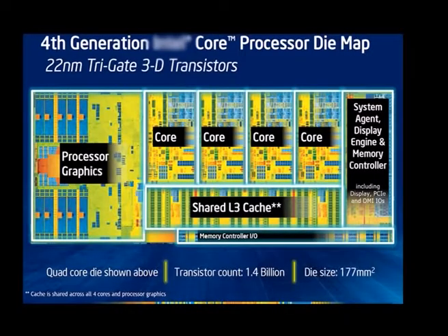The CPU with 4 processing components is called a quad core CPU. The presence of multiple processing units facilitates simultaneous arithmetic and logical operations, leading to increased capability of handling multiple programs or users. Also, techniques can be used to divide a single large program among multiple cores and finish the program in less time.